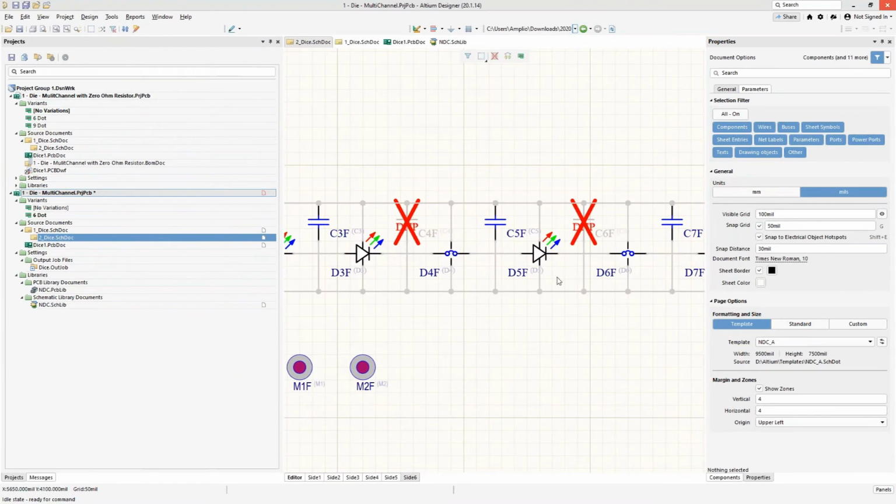So you can see that these have been put in and there's no errors or anything like that, and we'd be good to go. Well, if we do add an alternate part in here, guess what? It does actually impact the net list. So I do actually have to push an update ECO over. So I will bring up the ECO. So let's go here into our design update.